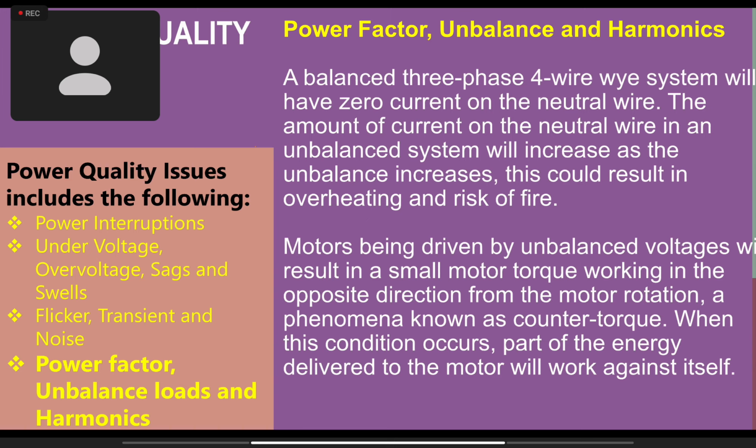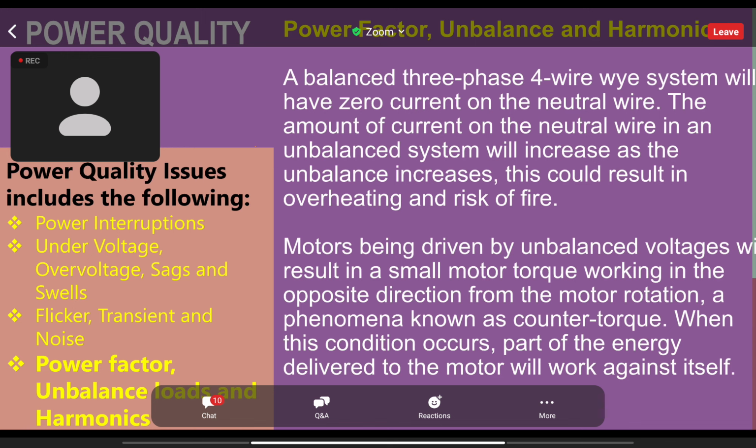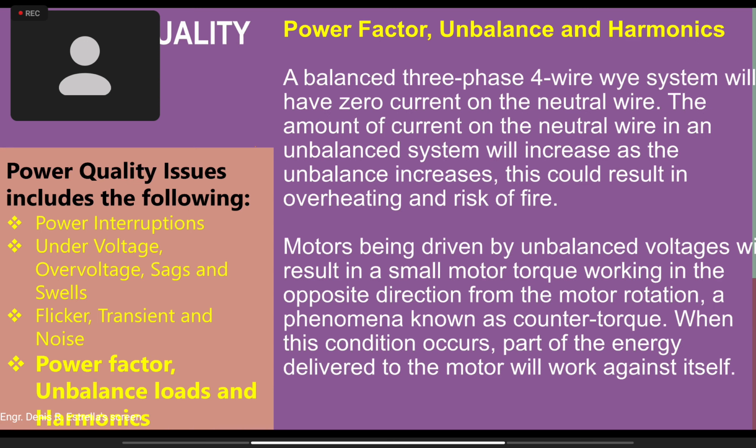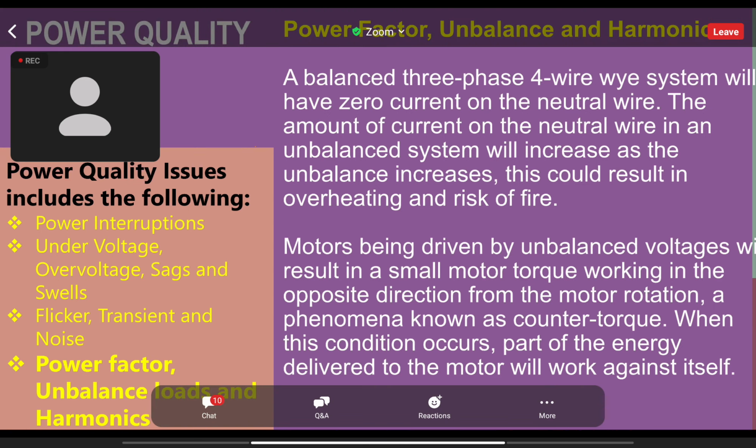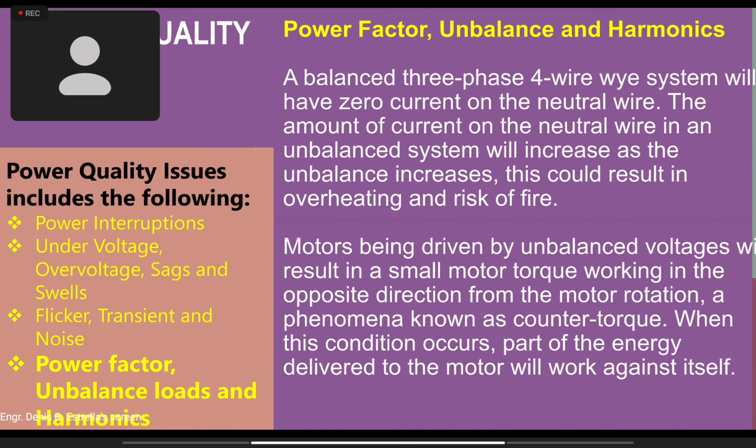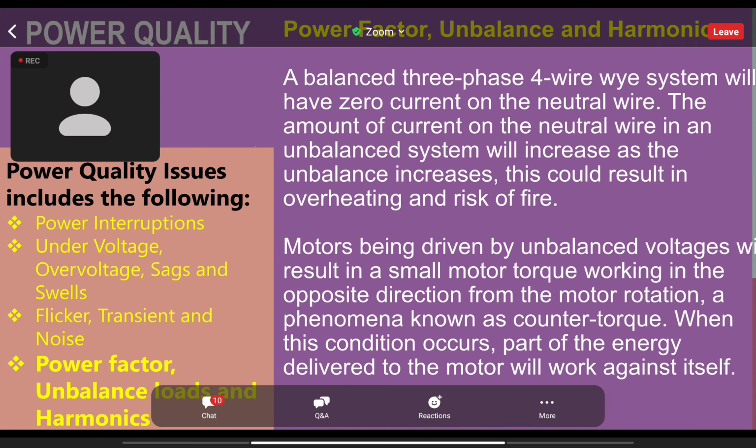And if that amount of torque is severe, it can lead to overloading if the driven mechanical load and the motor was designed just sufficiently enough according to the load requirement. Hindi malaki masyado yung allowance, so ma-overload yung electric motor natin because of this effect of the counter torque due to unbalanced voltages. Kaya kailangan din magkaroon ng balanced voltage. More than 5% is not good. So 5% is tolerable.